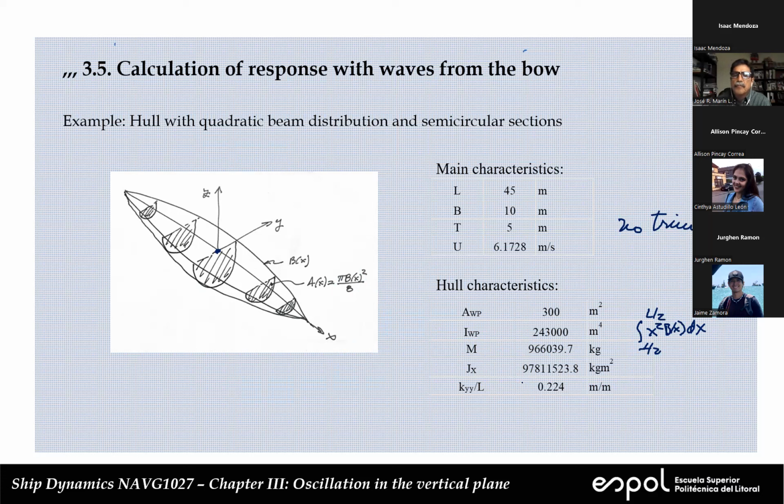This is the second moment of the mass distribution. So this thing here is similar to this one, okay? And finally, after we calculate this, we divide by m, okay? So kyy squared is the inertia divided by the total mass.